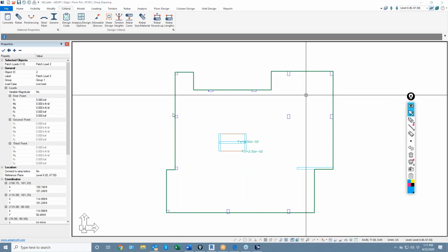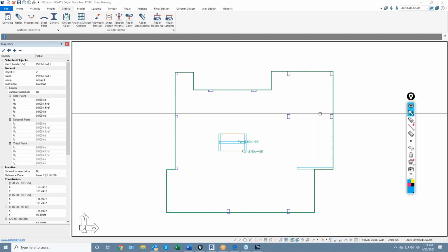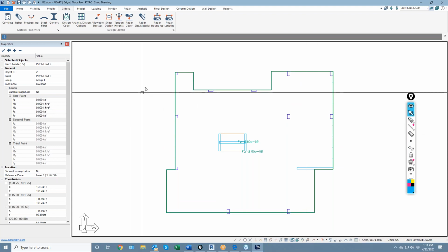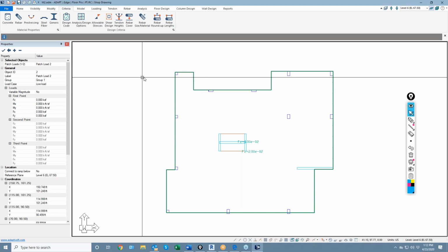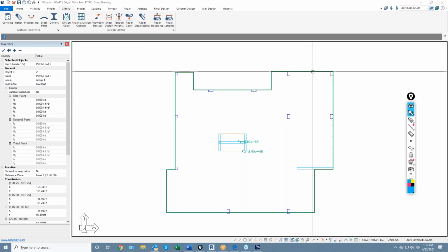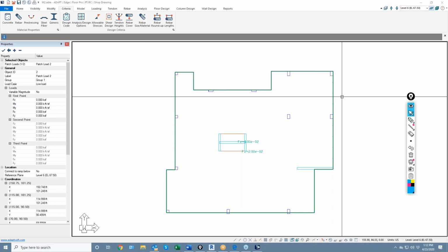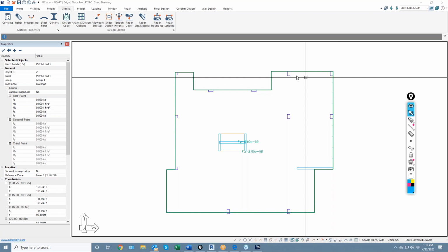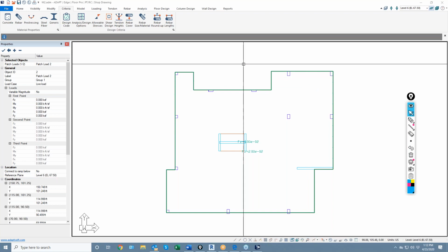There's a question. Quick question on live load reduction. Can they overlap, or do we need to keep them separated? Pavel, I don't know if you're referring to the actual subregions overlapping or the loads themselves. Yeah, so the loading can overlap. It's just if they do overlap and you have a subregion that has two loads in that subregion, then both loads would be applied in the subregion. But you can only assign one load to be patterned.